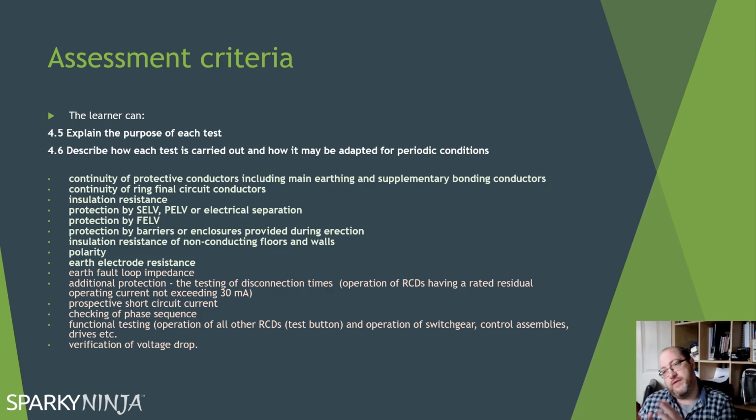This is a big problem we have over in the HV world, where we don't have sufficient functional operation of the switchgear because no one likes to go near it. But yeah, you need to verify the functionality and the reliability of every device. This will include, later on down the line, devices that are supposed to disconnect, like arc flash detecting devices as well. So this will be interesting to see how we're going to do that.